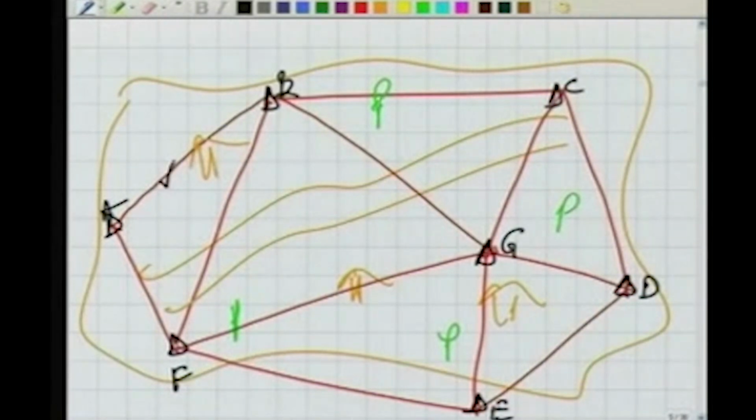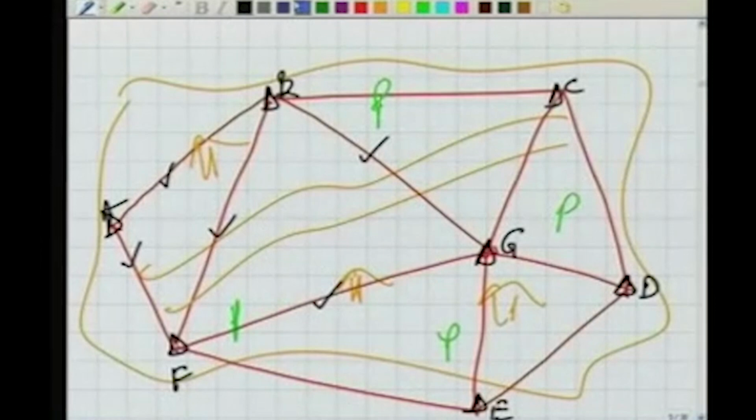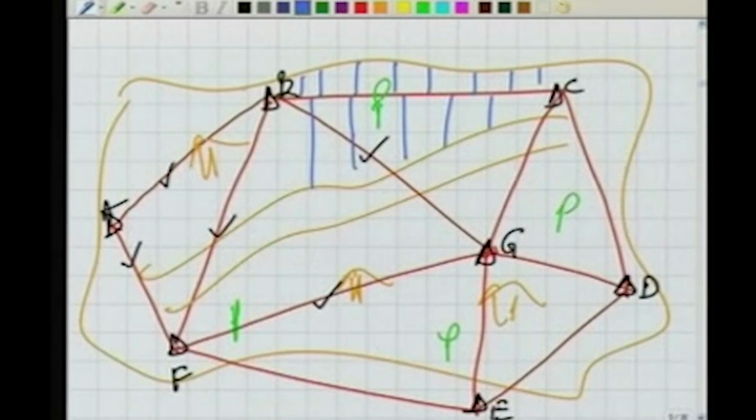I can measure all these lengths, that is not a problem, because I have ensured that these lines pass through nearly flat area. There is no obstruction. Also at the same time, you can see that taking the offset is easy. I can plot this boundary here. While plotting this boundary, I am plotting with respect to the line BC, also this road. For the boundary here, I can take these as the offsets.